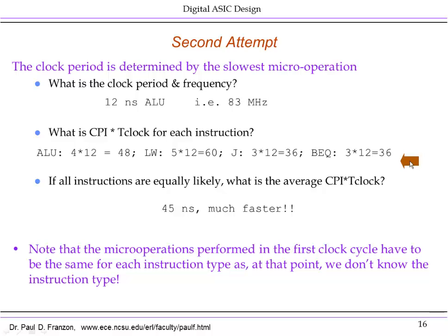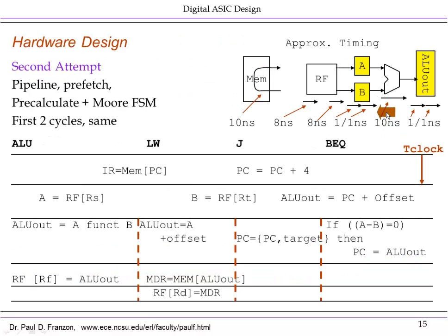It's worked out that making the critical path faster at the expense of adding cycles has worked out in our favor because we made the critical path much, much faster. It's more than twice as fast than it was before. Now, of course, it depends on your design whether this works out in your favor or not in general. But in this particular case, it's made the design much faster. At a very small additional area overhead, we've only added 3 registers to the design. So the area per unit performance is also much better than it was in the previous version.